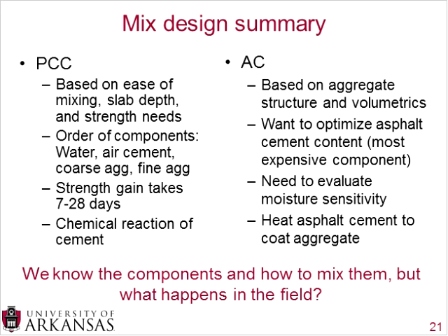So in summary, for mix design, for PCC, you do your mix design based on the ease of mixing, your slab depth, and other strength needs. Then you simply go in order of the components. So you start with your water, and then I have a mistake here. You start with your water, then you go to your cement. The word air should not be in there. You start with your water, you go to your cement through the water-cement ratio, you determine your coarse aggregate, and you simply subtract those three values in order to find your fine aggregate.